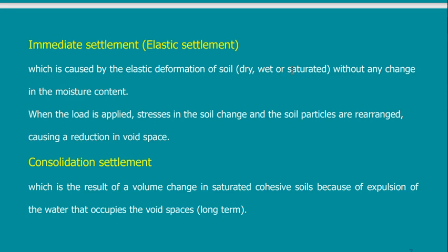Why is it not important? Because we said that the permeability is very high. So whether you have water or you don't have water, if you have water, it will be expelled. If you don't have water, then you have voids, and the settlement will happen. So it's not an important issue, is it dry or wet?